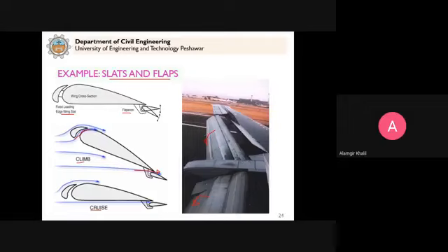And these flaps are up because the air will come and move in the upward direction. They will push the air in the upward direction, so this will help reduce the lift force acting on the plane wings. So this is how you commonly have seen or observed this situation while landing the airplane.